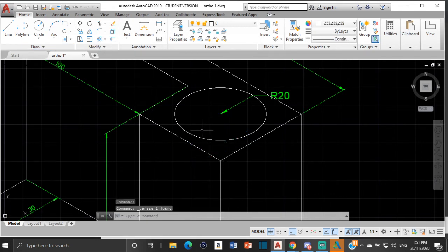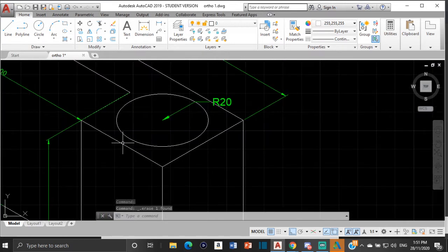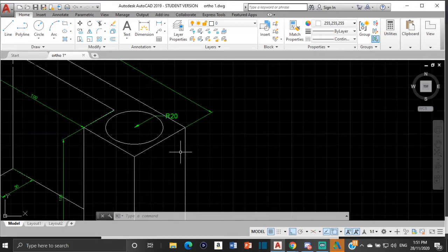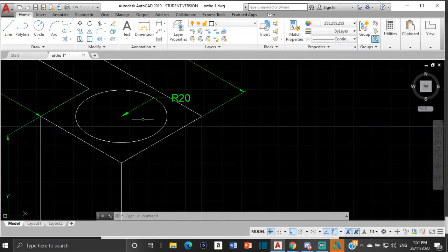All right, so it will tell you that the center of the circle is 15 millimeters away from here, and also 15 millimeters away from there. So you will know where the circle is located. In this case, I didn't have that information, but I know that the circle is the center of this entire box. So if I find the center of this entire box, I will be able to draw my circle. But on a different drawing, you will be given the position at the center of the circle.